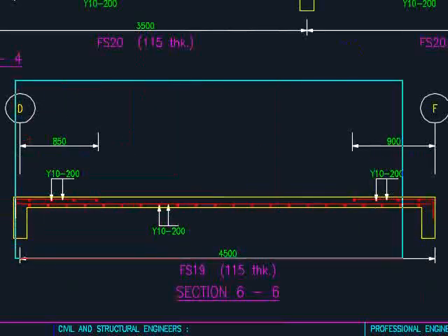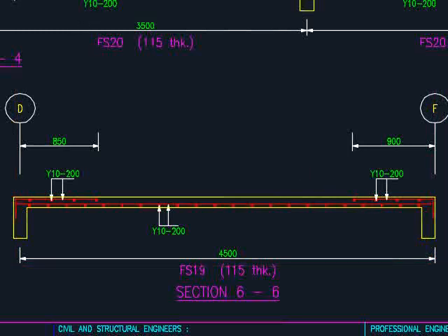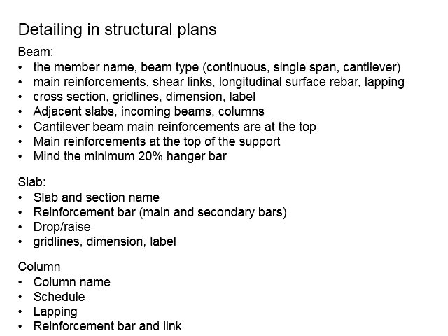This is the typical design for a single unit slab. Although you know that you can actually design the slab to be simply supported, however, for reinforced concrete structures, there is no definite pin support. Normally, we will also provide the top reinforcement bar at the support to ensure the integrity of the structures. What we see here,